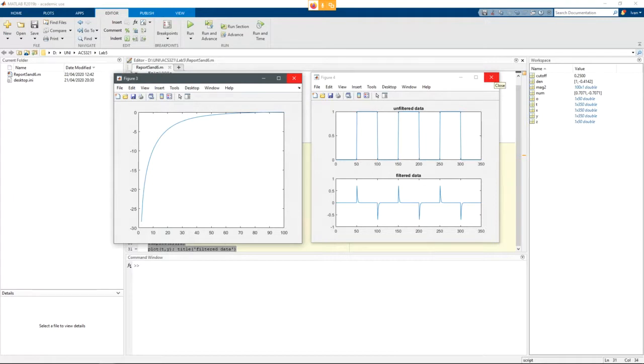But what I hope to see in edges, when we have a sharp change, for example, from 0 to 1, here we have high frequencies because the change is quick. Then we have our signal always 0 or 1. There is not that much change. So this part of the signal contains mostly low frequencies. Again, when we drop from 1 to 0, we have a sharp change. So mostly our signal has high frequencies in these parts.